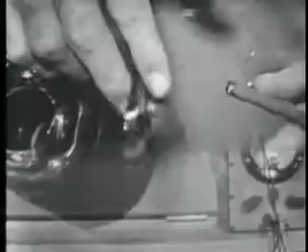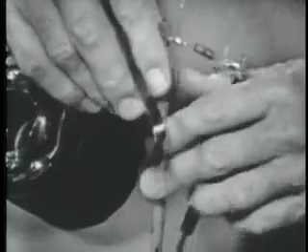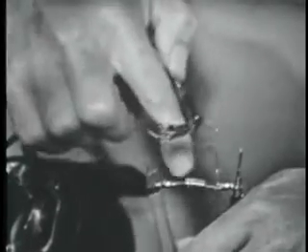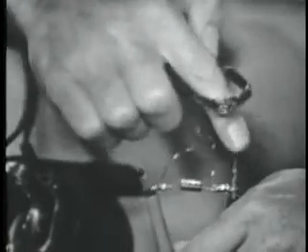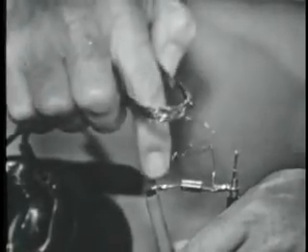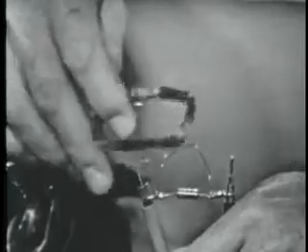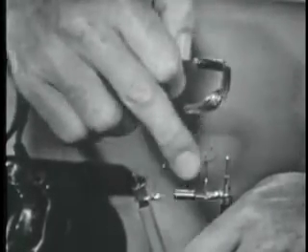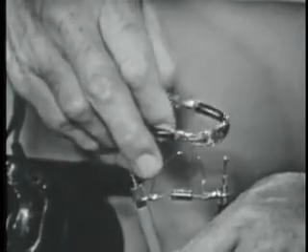Now, why don't you explain what you're going to do, Bob? All right. This is a coil of wire. The ends of the wire are connected to a resistor that is connected to the leads on our PSM6. And the object is, if we get current to flow in this loop, we'll have current flowing through this resistor, we'll get a voltage drop, and we'll read the voltage on the PSM6, okay?